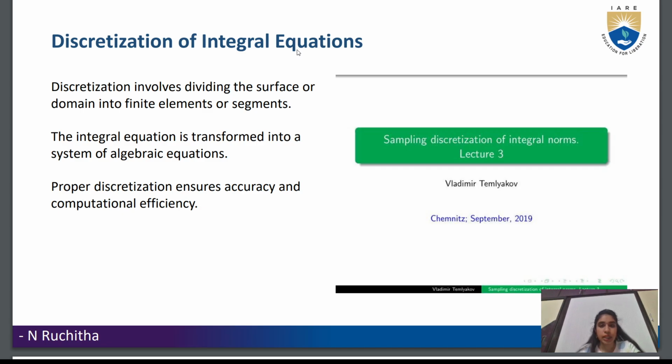Discretization of integral equations. The domain is divided into elements, surface patches, or control volumes with nodes. Integral expressions are approximated using numerical quadrature, which results in a matrix system typically linking radiosities or intensities across the mesh. Accuracy depends on mesh refinement, the order of the quadrature scheme, and the treatment of angular discretization, for example discrete ordinates.